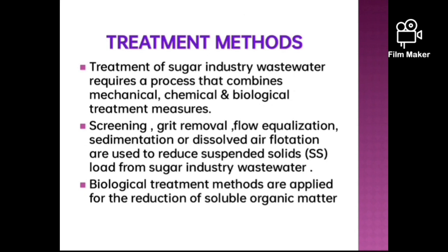Treatment methods. Treatment of sugar industry wastewater requires a process that combines mechanical, chemical, and biological treatment measures. Screening, grit removal, flow equalization, sedimentation, or dissolved air flotation are used to reduce suspended solids, that is SS, load from sugar industry wastewater.